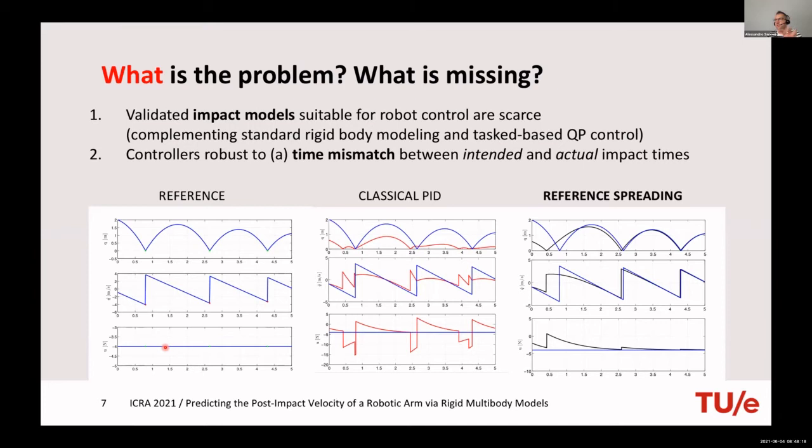In this case, there's no input. Like I said, imagine that there's an actuator that can control the vertical direction of the ball. And this is just the reference. You want to start tracking this reference, so you would like to put a controller. You start from somewhere else. And then at the moment you make an impact, the impact usually is not exactly where you want it. So if you use standard ideas of tracking, then you have a problem, because you had an impact. You would like to start following the next reference, but if you do not have a strategy that is aware of impact, it will try to follow this reference trajectory again, making the system impact again, and so the performance will be extremely poor.